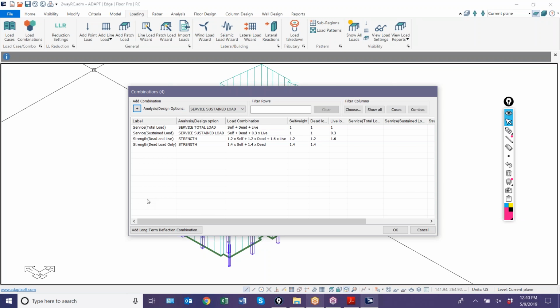And then also, we want to provide the option for wind loading, for example, for the user to say, I only want to consider ASCE 7 wind cases 1 and 2, not 3 and 4, which would potentially create an additional 12 to 24 different permutations of combinations for each combo times however many combinations you're evaluating. So that blows up the number of load combos. So that's the reason it has yet to be released.